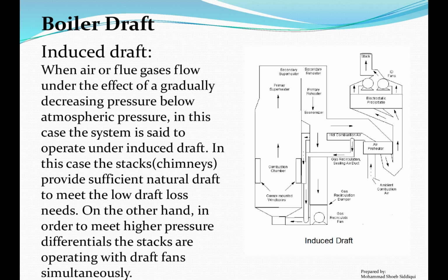Induced draft. When air or flue gases flow under the effect of a gradually decreasing pressure below atmospheric pressure, the system is said to operate under induced draft. In this case, the stack's chimneys provide sufficient natural draft to meet low draft loss needs. On the other hand, in order to meet higher pressure differentials, the stacks operate with draft fans simultaneously.